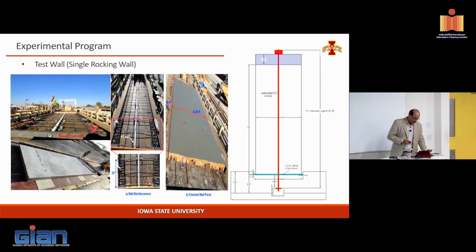So the only steel that you see here is a shrinkage control reinforcement. So cast in place structure will look very different, very congested amount of reinforcement. So now we're taking a precast, you're going to rely on jointed concept, we are going to allow it to rock, and look at how much labor one can reduce by getting rid of a lot of the reinforcement.